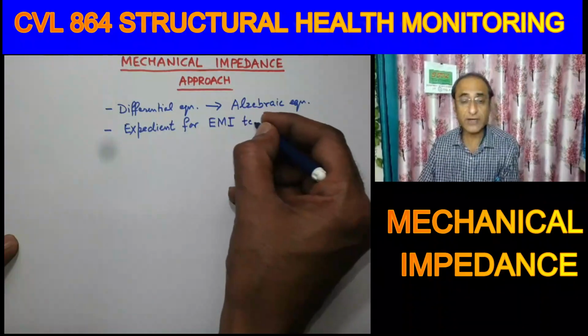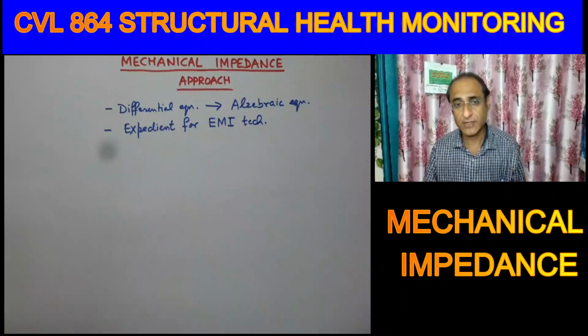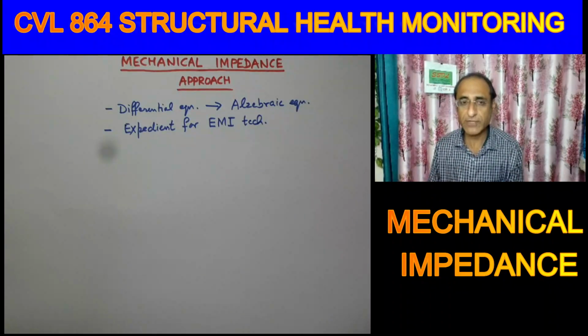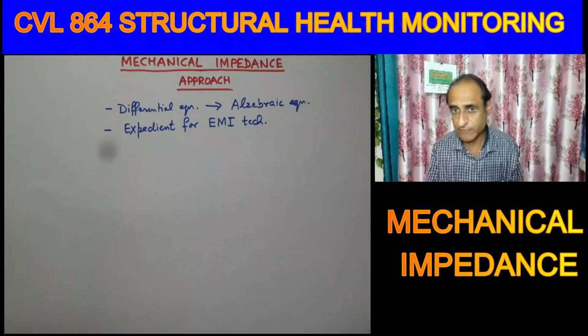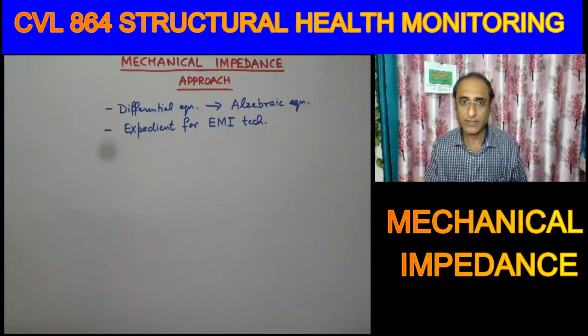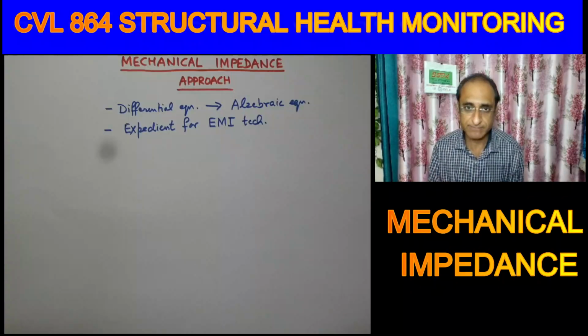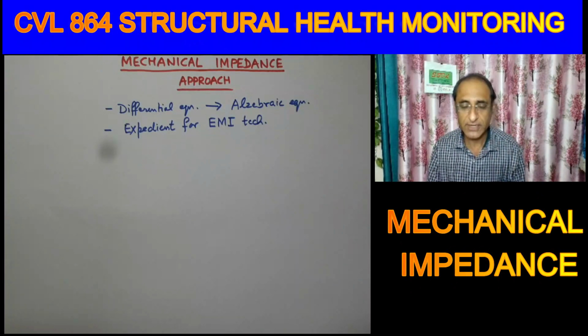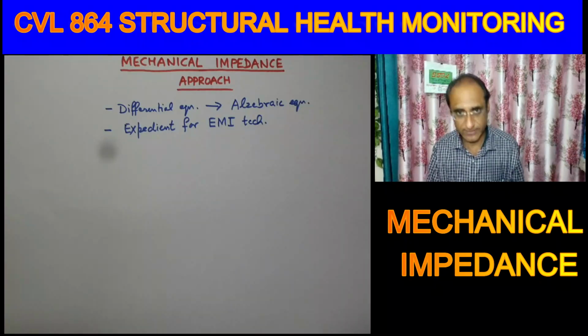So what we are doing today, we are forming the background for the EMI technique. We will derive the complete governing equation of the EMI technique, and that's why we have introduced damping. So we have seen that if there is damping in the system, then the displacement and the strain will lag behind the force or the stress. If there is no damping, then it will be in phase, no lag. Alright.